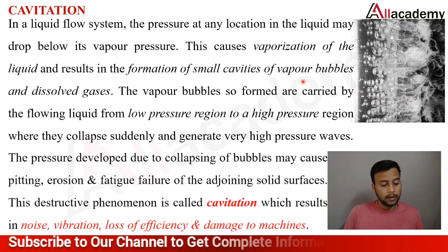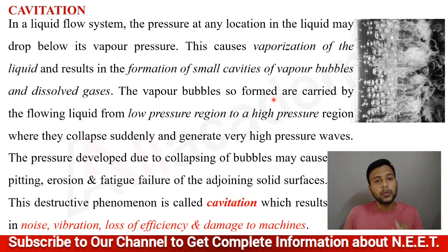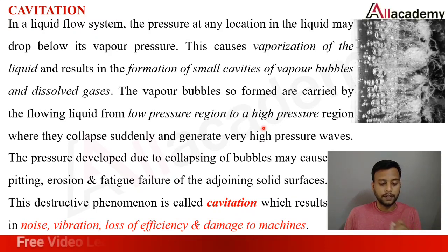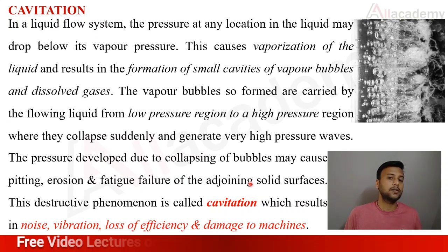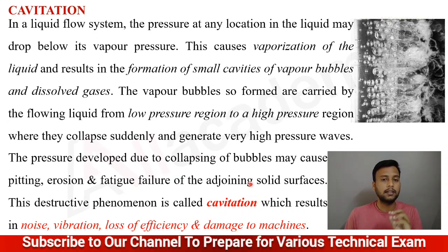The pressure developed due to the collapsing of bubbles may cause pitting, erosion and fatigue failure of the adjoining solid surfaces. I will show how this cavitation affects the solid components of turbines and compressors, or the blade surfaces, in the next slide.